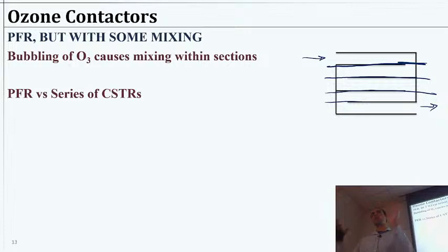The whole system would be better described as a series of several reactors, where, for tracking some number concentration of microbes, we'd have our first section, a CSTR with N0 leaving out to N1. N1 then comes in, and then N2 goes out, and so on. And finally, N4 to N5.